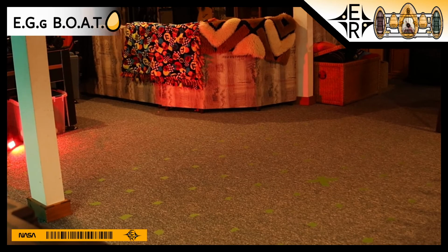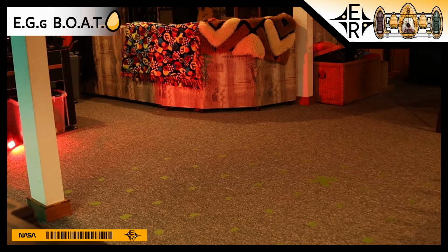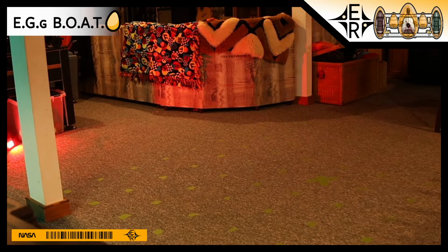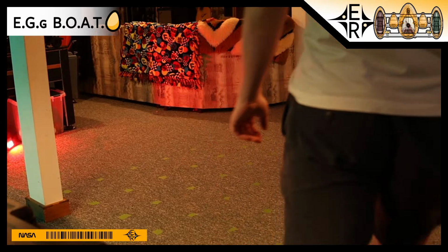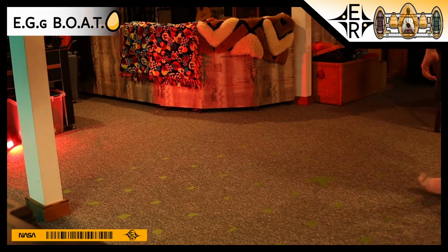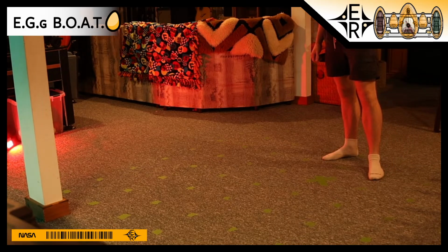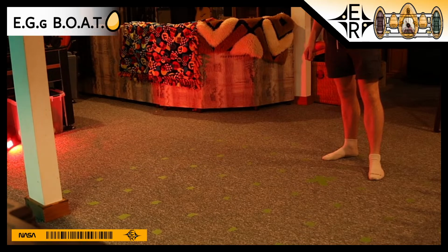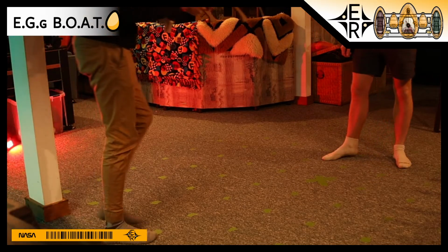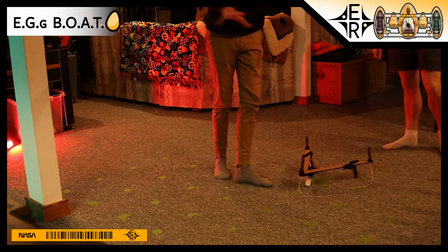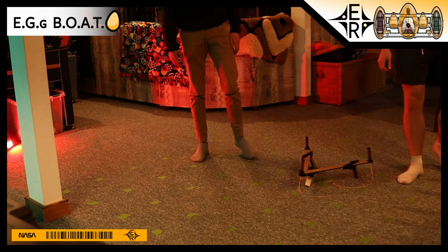These tests are going to allow us to use the phase comparison system once everything's wired up and test it using what's called correlative interferometry, which is basically we're going to take the antenna platform, which I will bring over. Once it's set up electronically, we should be able to calibrate it by moving the beacon around it at different placements. Okay, so you got a 9x9 grid set up here.